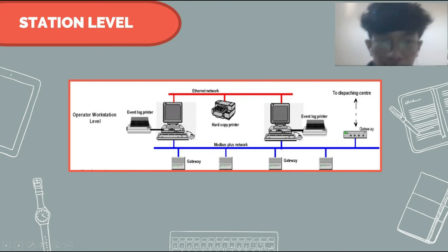The master station sequentially scans the RTUs by sending a short message to each RTU to see if the RTU has information that needs to be reported.